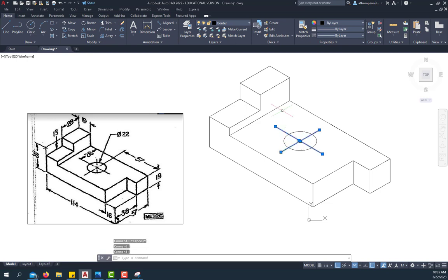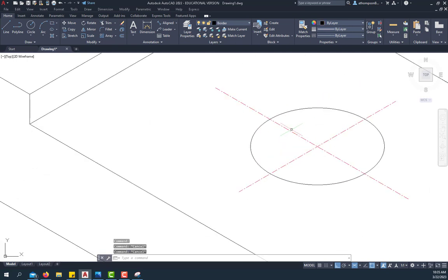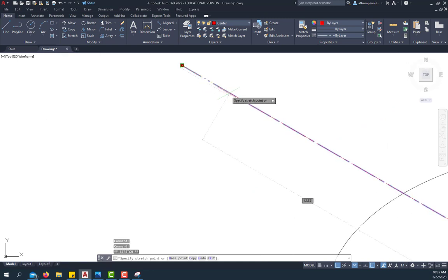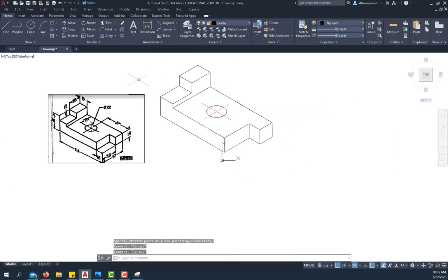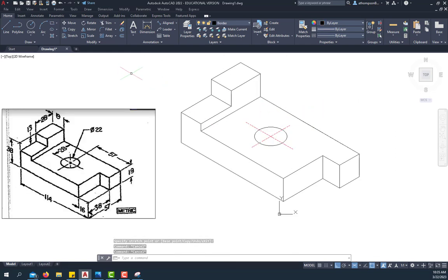So create something that's pretty uniform in shape, and then come up here and turn it into the center layer. Now remember, this is in metric, so it's going to look like your center lines are just way too many dashes. But when we go over to paper space, we'll be just fine. So keep it like it is for now.